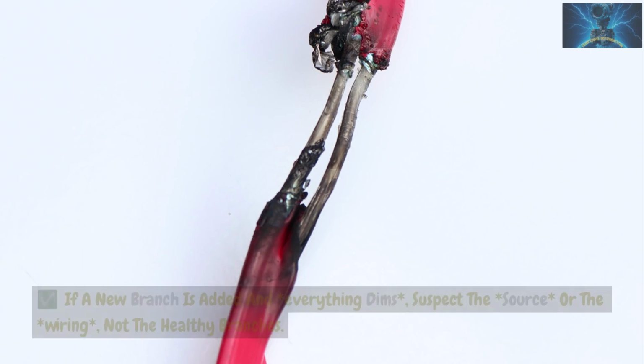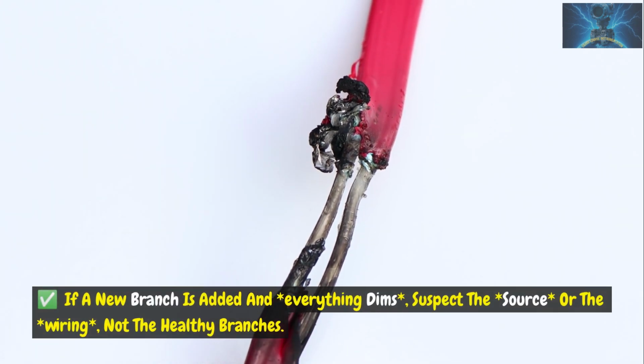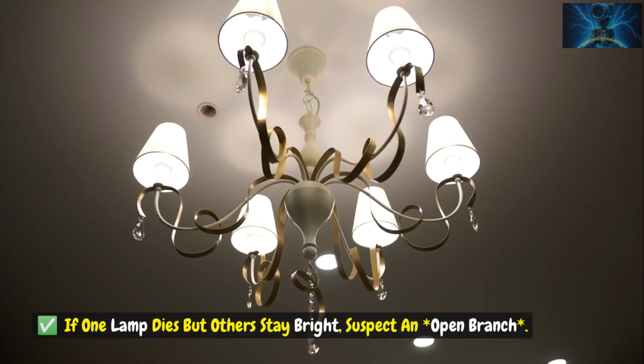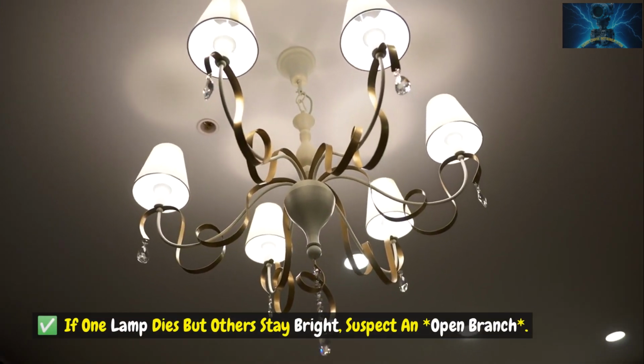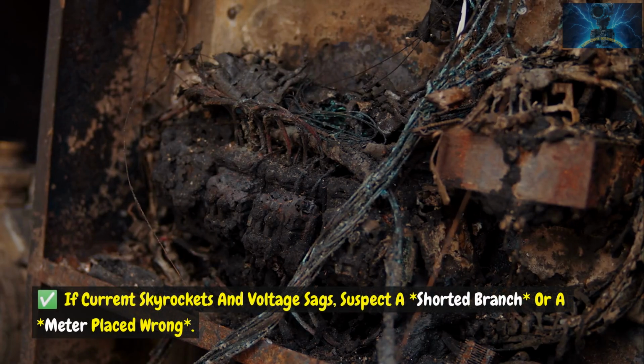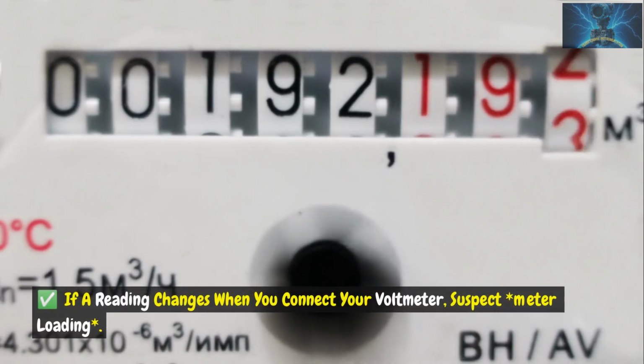Quick self-check. If a new branch is added and everything dims, suspect the source or the wiring, not the healthy branches. If one lamp dies but others stay bright, suspect an open branch. If current skyrockets and voltage sags, suspect a shorted branch or a meter placed wrong. If a reading changes when you connect your voltmeter, suspect meter loading.